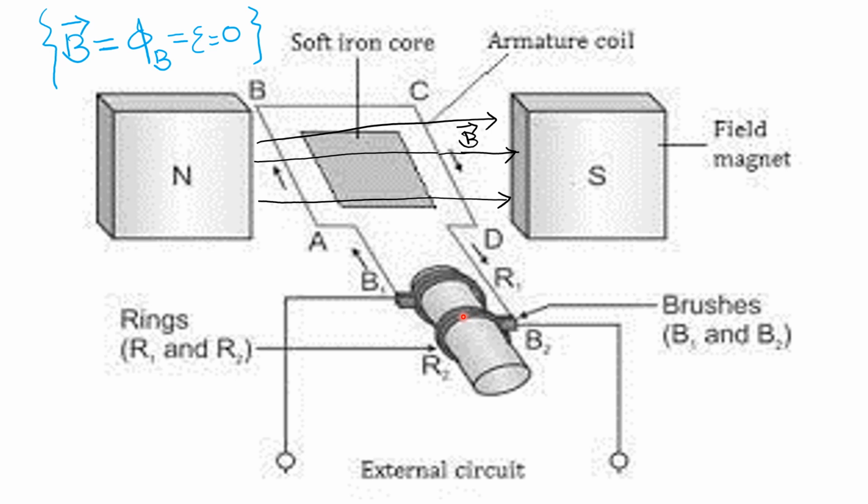These slip rings have a very important role. Since the armature is based on copper coils, and these copper coils have two corners, one corner of the copper coil is welded with one copper slip ring, and similarly the other corner of the coil is welded with the next slip ring.